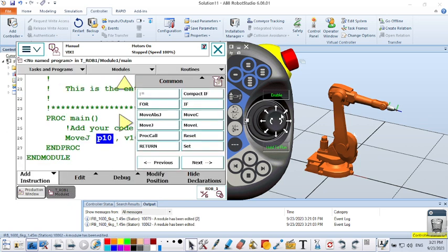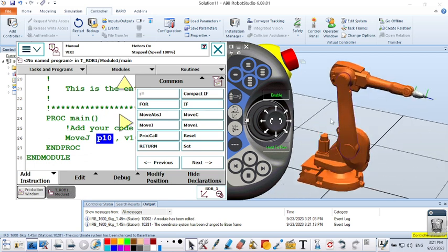After that I'm moving the robot to a certain position. Here in the individual jog motion that is available, I make this into a linear mode. Just click this icon, this option, for the linear option. You see the linear option is changed. Now I am moving the robot to one particular point.